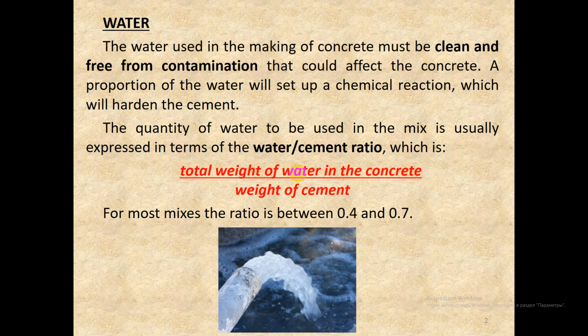Eurocode EN 1008 specifies the quality of water required. A practical means of checking that water is acceptable is to make trial mixes using the available water.